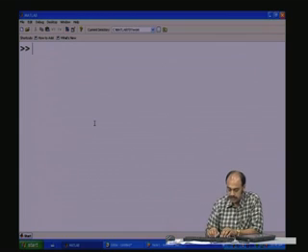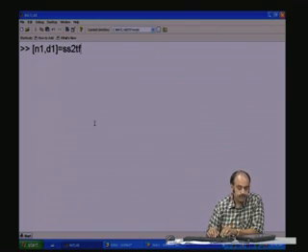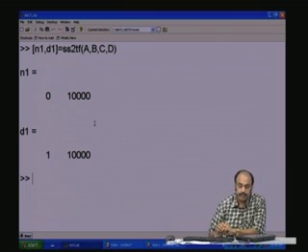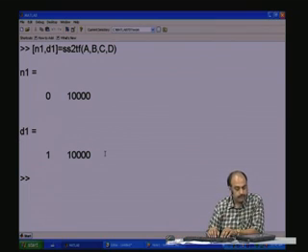do this particular conversion. Let me have a numerator polynomial n1, a denominator polynomial d1 of the transfer function, which should be obtained after the conversion SS to TF, state space to transfer function, and we have A, B, C, D matrices. So, this A, B, C, D matrices should get converted to the numerator polynomial, denominator polynomial. So, this is the numerator polynomial function of S, this is the denominator polynomial function of S. Of course, it does not look like a transfer function.